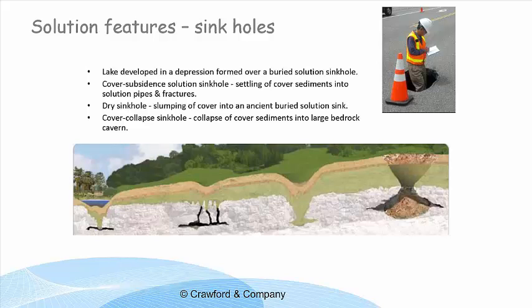I'm going to focus on this one here, because this is the one that we see a lot of. It's what they call a cover collapse. And what you've got is clay, if you remember, we've got a lot of clay. Clay tends to stick and hold while a subterranean cavity opens up. So you end up with a hole, and then eventually one day the clay collapses in, and anything on top of the clay is going to follow. Yeah? So you can get quite dramatic ones.